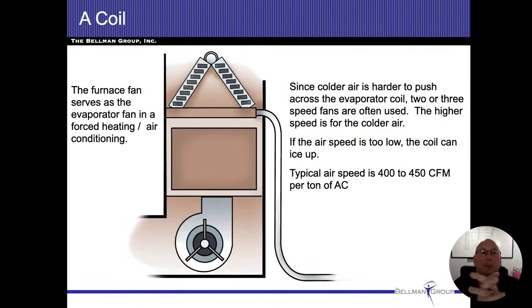The indoor coil, some people refer to that as the A coil. It only gets its name because of the shape that it's in right now. Because it's up and down like the letter A, that's the only reason why we call it an A coil. The true name, and the name I want you to remember, is evaporator coil. Mainly because this is where we're converting, again, from a liquid to a gas. So we're vaporizing, so we're going to call this the evaporator coil.